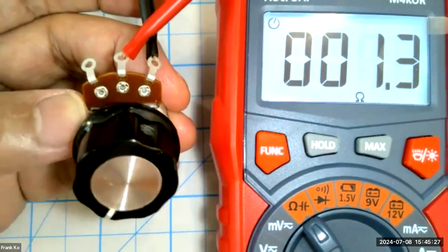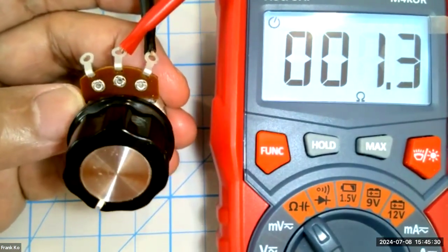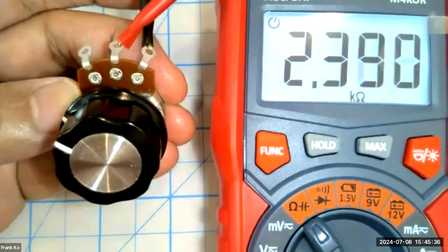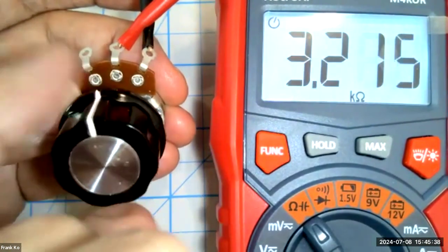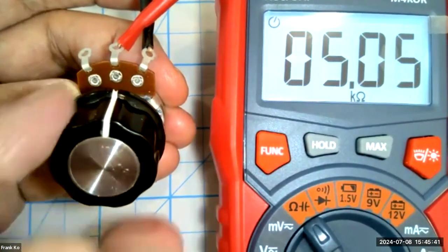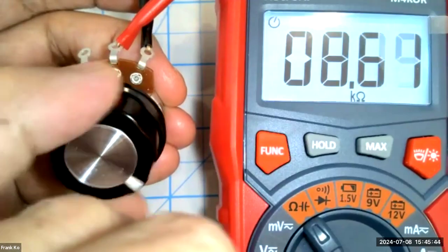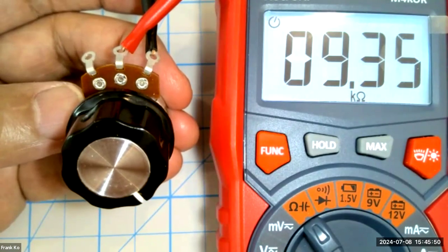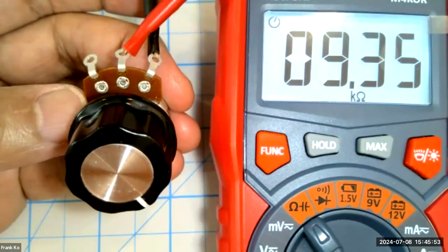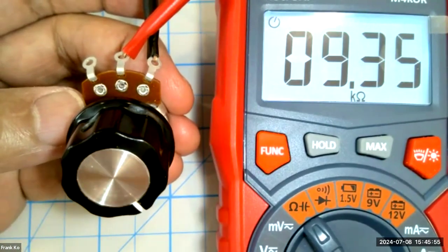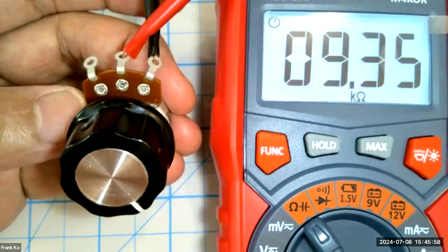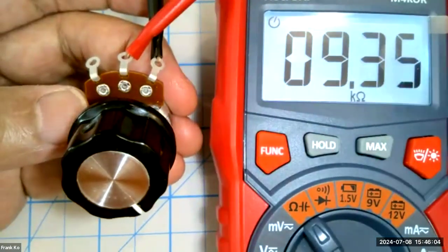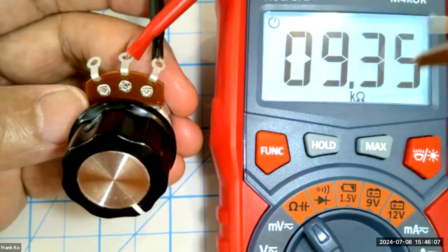The knob is at our traditional minimum if this were a volume control. And then if I were to rotate this in a clockwise fashion, you can see I'm increasing the amount of kilo ohms, increasing to about halfway, and increasing until I reach all the way over, and I will reach the maximum of our 9.34 or 9.35 kilo ohms. So now we have a rotation that is consistent with increasing the amount of ohms. And all that we've done here is use the center and this outside pin versus the center and the left outside pin. All right.